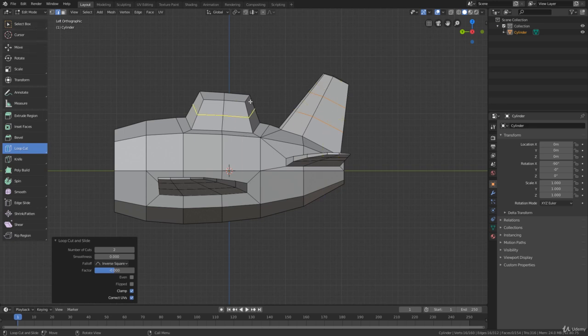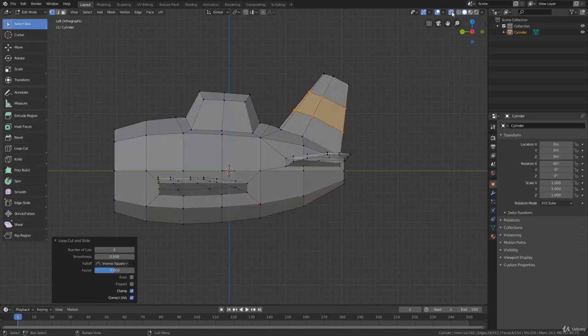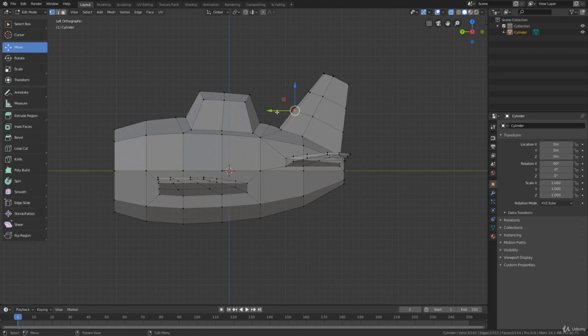So to do this, I will activate the Select Box tool to select the vertices from both sides, and activate the Vertex Selection mode. And I need to activate the X-ray mode so that I am sure that when I select things from one side, the vertex on the other side are also selected. Okay? So now I can create a selection window to select these vertices here and move them forward a bit on the y-axis.